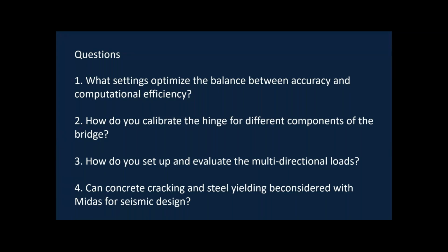So we have seen that mostly engineers, for the particular representation of the data in this pushover analysis, will go for the bilinear type of plastic hinge, or at most the trilinear type of plastic hinge, which is a good representation of the hinge data. And regarding the calibration, it can be done on the basis of the moment curvature curve that is being generated for that particular section.